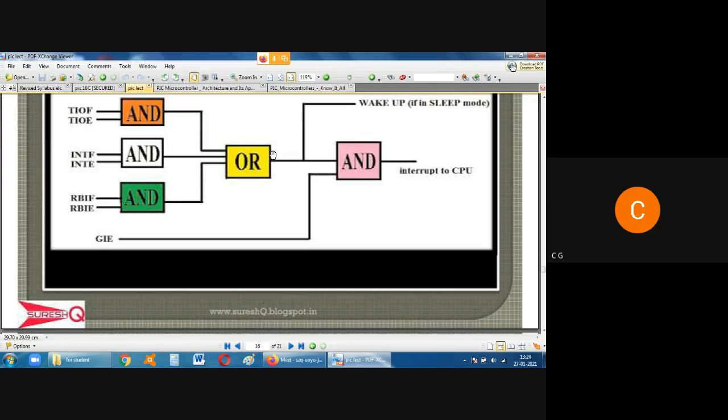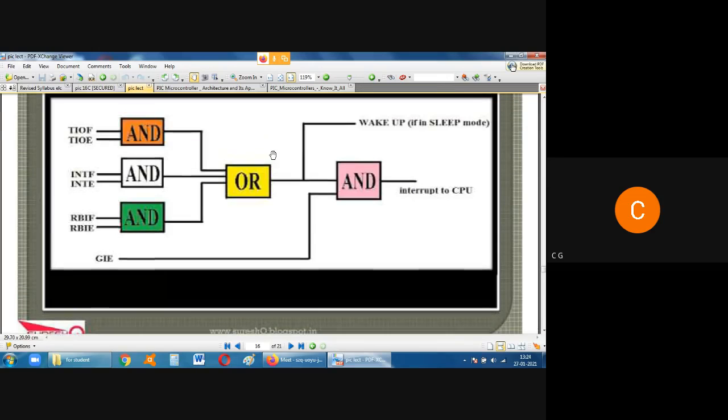Let us utilize all these gates. First check the gates and then utilize them along with the adder subtractor functioning. Let us make something different called a comparator, and then you give some two values, 0 1 1 0, 1 1 0 0, and see what output is being given.